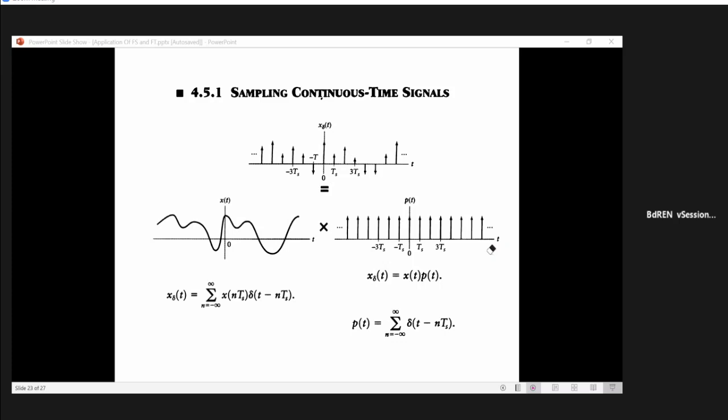That holding can be made by zero order hold, that means flat top type. That means the signal is acquired fast, sensed fast, and the amplitude is kept constant. But in other cases, it can change linearly, okay? That is called first order hold. There are so many things there.